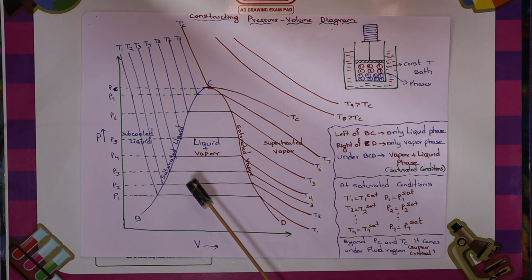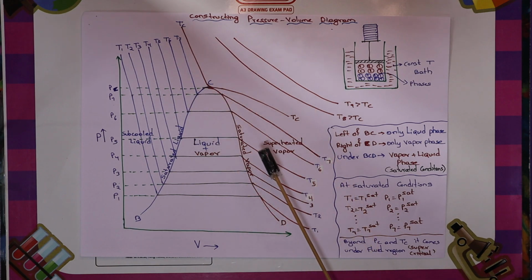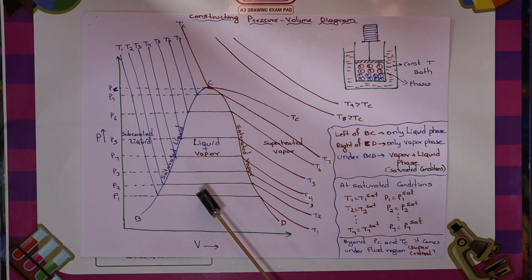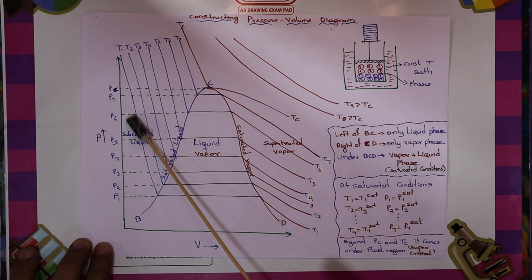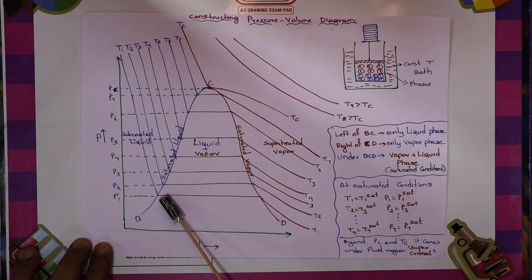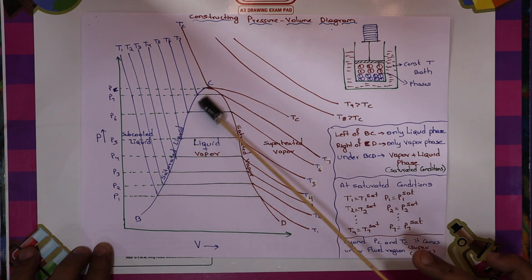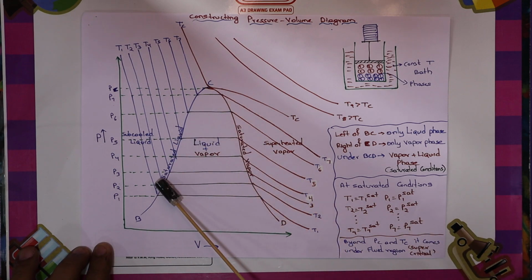This is all very important because this is the basic background to learn PVT, pressure, volume, temperature data. Wherever it touches, you can see at T1 temperature, if you maintain the P1 pressure, for example, wherever it touches this particular blue curve or red curve, those are called saturation pressures and saturation temperatures.